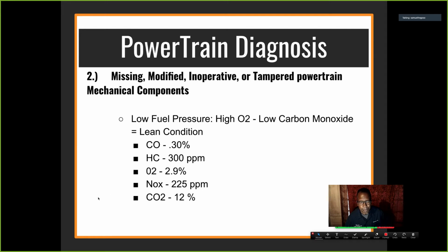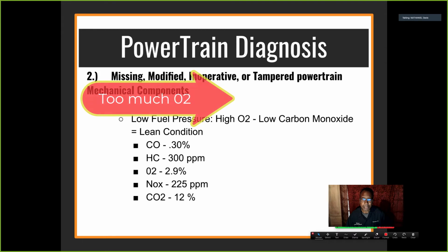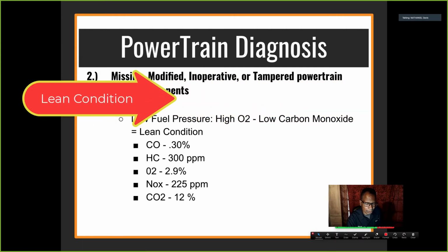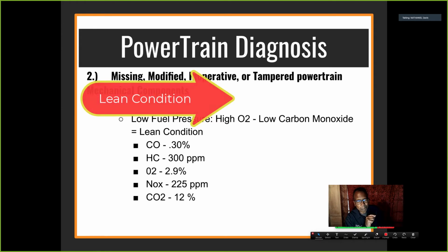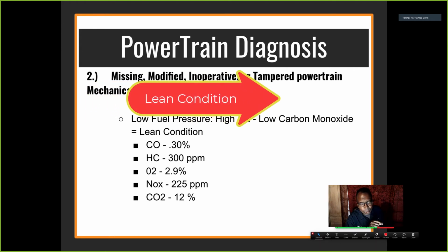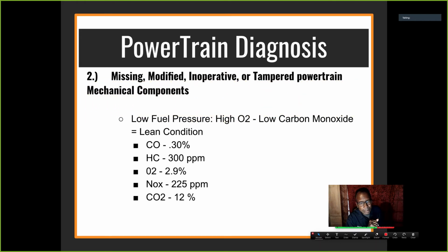Let me ask you something. Yeah, go ahead. The majority of times that you see high levels of oxygen, it would probably mean there's not enough spark, right? Too much air. It could be spark or a leak. Or a leak. Oh, okay, or vacuum. Yeah, a vacuum leak. Well, a vacuum leak would drive it. Presuming that this car has no air pump, because if you have an air pump, it's going to be much higher.